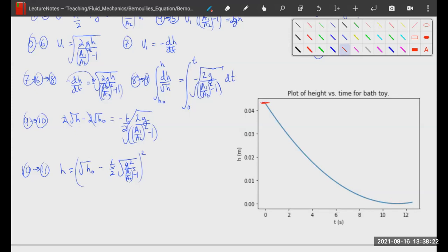You've probably seen a droplet held at the end of a syringe or something like that, where the fluid's not flowing out, but the surface tension is holding the fluid up. Surface tension can produce pressures, just like kinetic energy can, and changes in height. That pressure is almost counteracting the potential energy, the hydrostatic-ish pressure, but not quite. And so it's producing droplets until the surface tension is strong enough to just hold the liquid in place and prevent the container from completely draining, right?